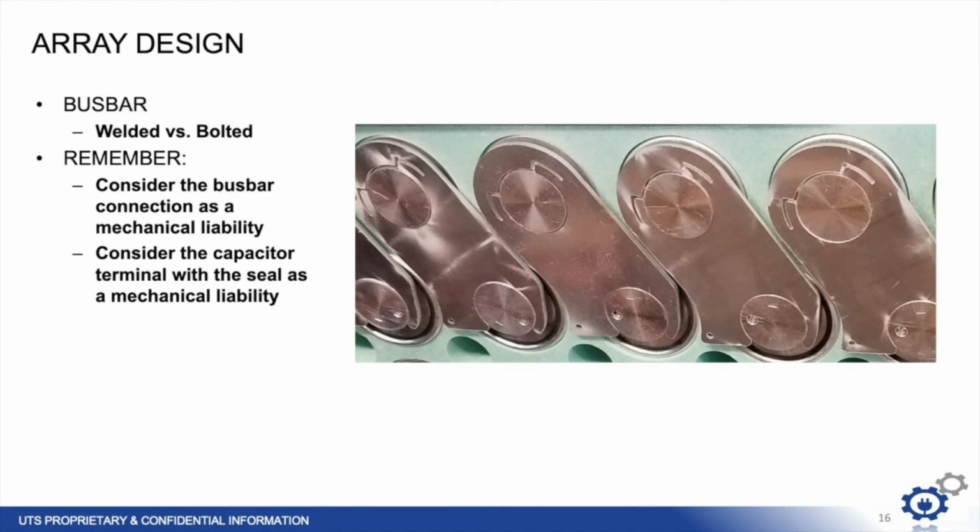So now if we look at the mechanical design needs, we find we need to protect the busbar connection and the cell crimp. In both cases, relative motion between cells can be the main problem. The connection can weaken to become a high resistance point, then a hotspot, and could eventually lead to cell failure. And the bus bars have now added a significant lever arm and a whole other body of mass tied to the crimped end terminal. This lever arm and added mass can make it easier to fatigue that crimp and seal.